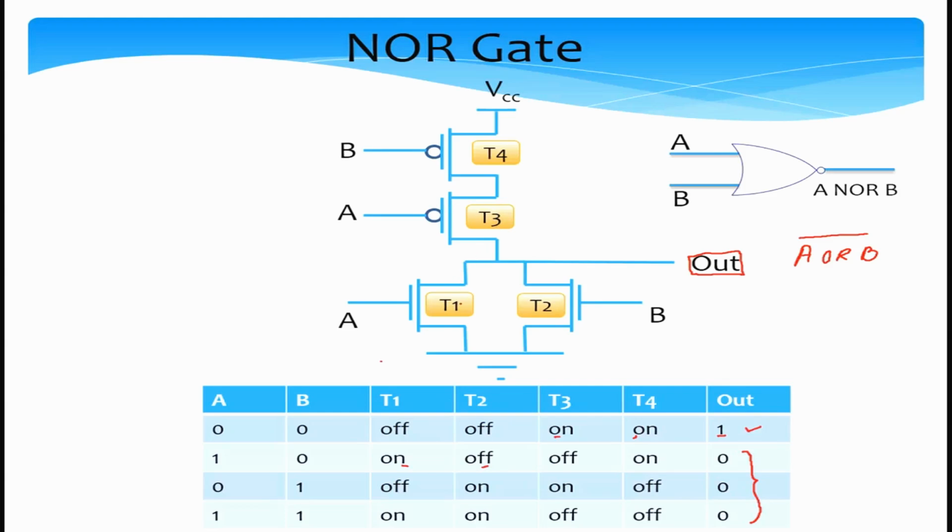But what we have over here is that the transistor T1 is conducting, so the output terminal is directly connected to ground. Because this transistor T1 is conducting, essentially we can add a straight line over here, directly connected to ground. As a result, the voltage at the output terminal is equal to the ground voltage, which is 0, and thus the output is a logical 0.